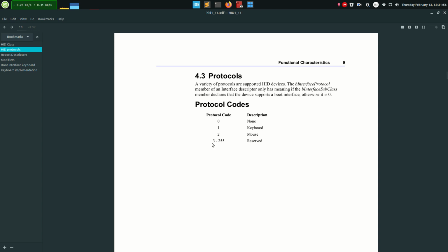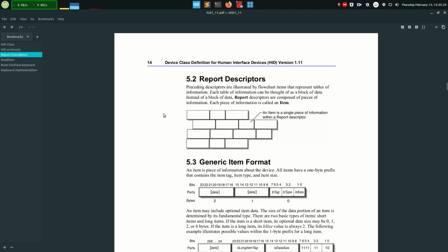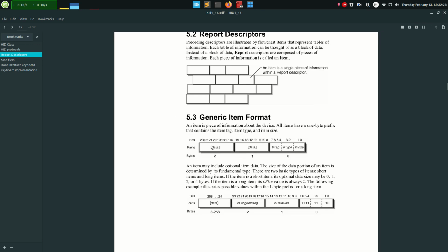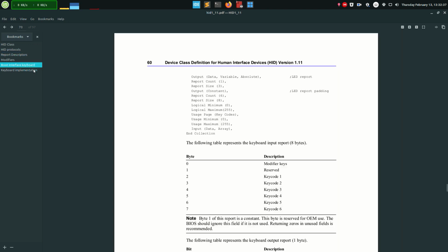The next thing you need to know is that the USB specification is very high level, it's very complex. It's not like SPI or I2C. It's in the form of packets, and the packets are large and have a lot of different parts, but the part of the packet we're concerned with for HID devices is the report. And again, the report is quite a big packet in and of itself. It has lots of information about the device, but the main part of this report is gonna be explained here. So the report is combined with your data and a lot of preamble and other reserved parts, but the part of the report we're going to be talking about is the body that we're going to be sending.